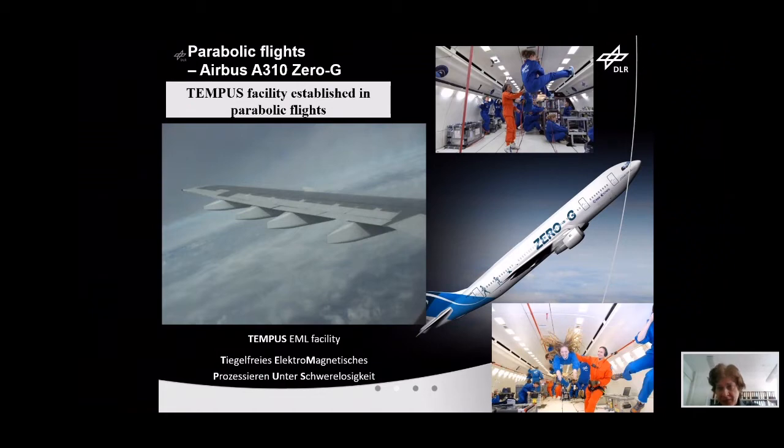In principle, it's enough to have information because, for instance, with regard to solidification kinetics, such small droplets, several millimeters in diameter, solidify in 10 to minus 4, 10 to minus 3 seconds. Because of this, if you have your droplets in an overheated state and already melted, and you have some cycles in order to destroy inoculators in the liquid, or big clusters, you have a more or less homogeneous microstructure of the liquid.